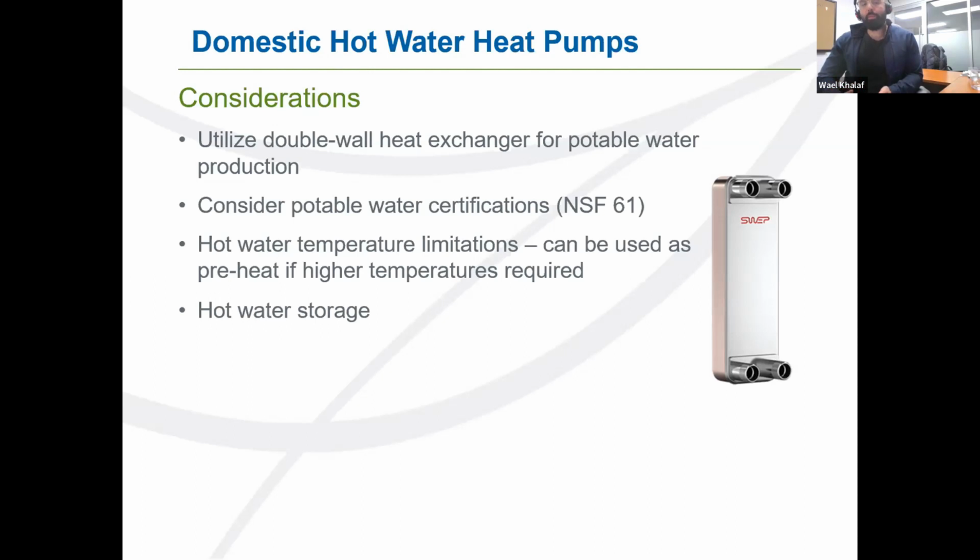of a very important consideration is everybody needs to understand that when we're looking at heat pumps or the heat pump concept for domestic hot water production, it is not an instantaneous domestic hot water production. It's not meant to be used that way. If it was, heat pumps for domestic hot water production as an instantaneous method would be extremely expensive. Our goal here is to have a smaller recovery rate using a heat pump, but have a larger amount of domestic hot water storage tanks to be used in conjunction with the heat pump.